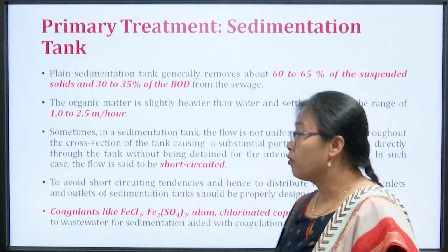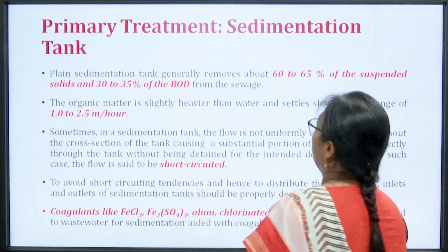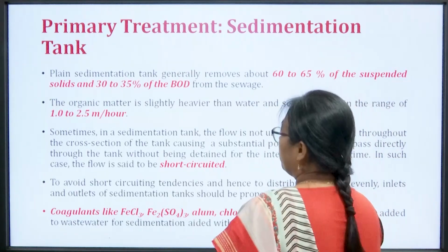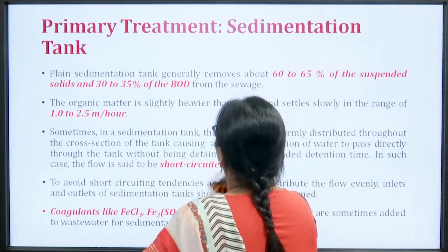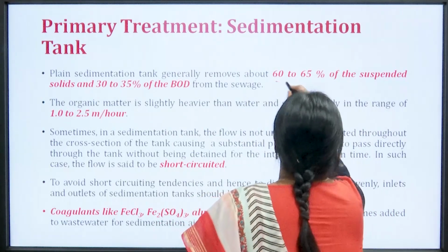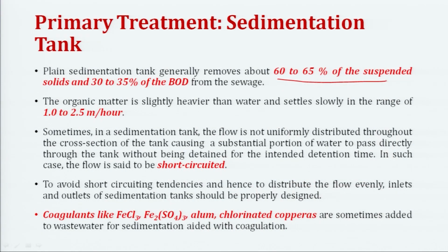Coming again to the sedimentation tank, as I have already said, in a plain sedimentation tank we generally remove around 60 to 65% of the suspended solids and 30 to 35% of the BOD.